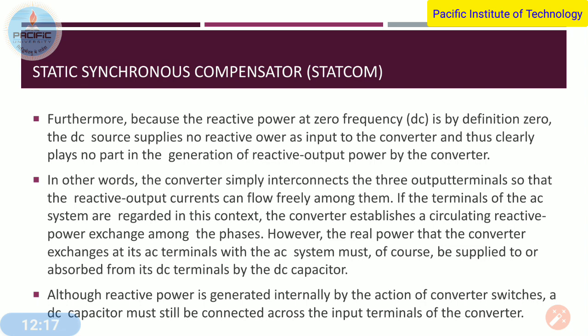However, the real power that the converter exchanges at its AC terminal with the AC system must of course be supplied to or absorbed from its DC terminal by the DC capacitor. So reactive power is generated internally by the action of the converter switches.